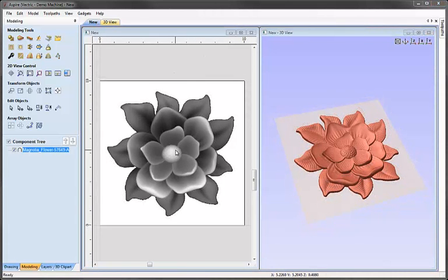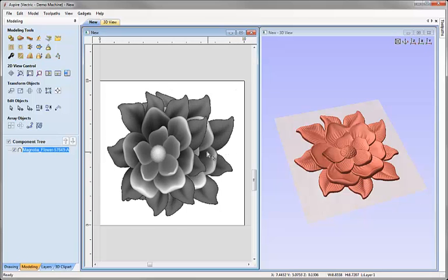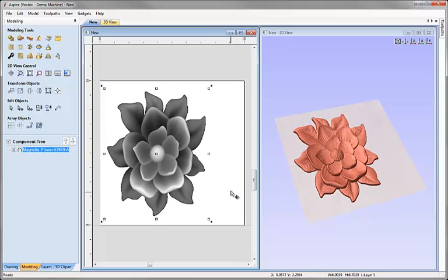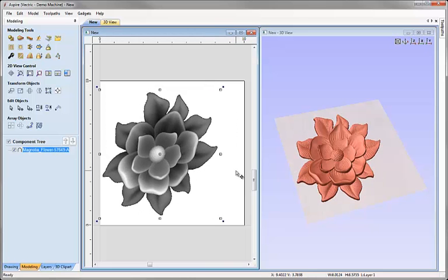As well as editing our part by entering values into the functions of the software, I can also dynamically change it. If I click on it again, I go into what we refer to as transform mode, and here we can see these little white and blue squares have appeared around the part, and they're handles that I can use to dynamically edit it. If I click on the one at the side here and drag inwards, you can see we can scale that down horizontally, or perhaps if I wanted to click on the blue node, I can rotate that around. So you can see it's possible for me to make edits without entering hard values and by just using my eye and the mouse in order to make changes to it.